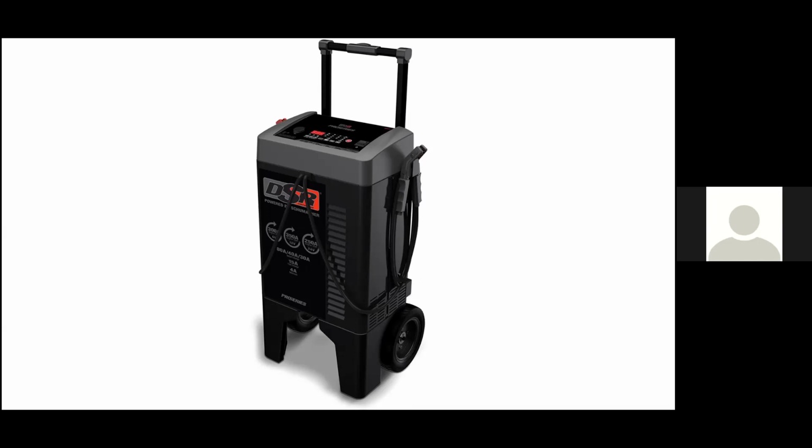So having proper battery voltage is really key on running scans, and even more key when you get into running calibrations. You should have something at your shop to provide good battery voltage while you're running these scans. Most of these scans only take a few moments, so it's not that big of a deal. But when you start getting into calibrations and diagnostics, you're going to have the ignition on for a much longer period of time, and that's where the battery voltage starts dropping down.